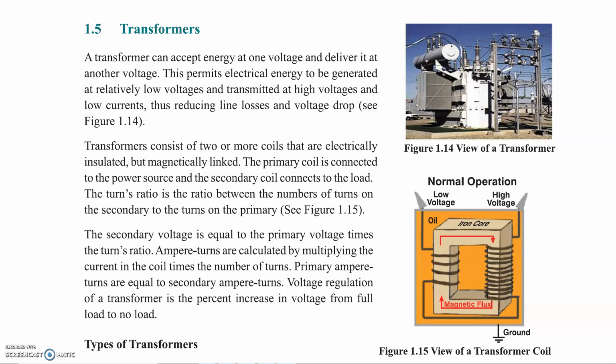So there is an increase of voltage that would take place from the full load condition of the transformer. When the transformer is fully loaded, the voltage goes down, and when we remove the loads one by one and completely remove the loads, no load is connected to the transformer, under that condition there will be the increase in voltage. So that increase in percentage form is expressed using this term called voltage regulation. That's another important parameter which is mentioned in case of a transformer by the manufacturer.